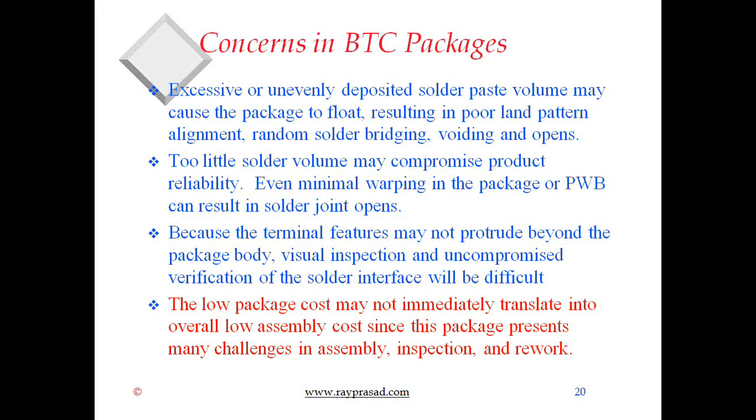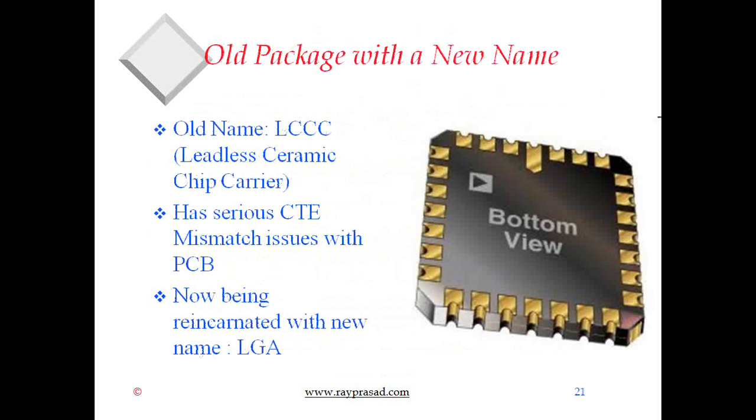Now, slide 21 here, just a nostalgic thing. This is a package that used to be called an LCC, leadless ceramic chip carrier. And this is even before SMT became very popular, early 80s, late 70s. And now we have reincarnated this package. It has come up with new names like BTC or micro lead frame, but it is the same package that caused us all kinds of problems. So just changing the name doesn't solve all those problems.